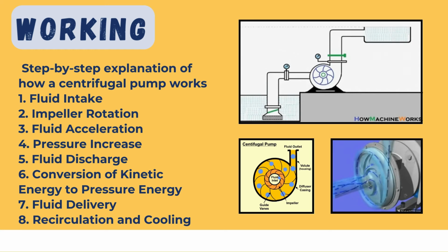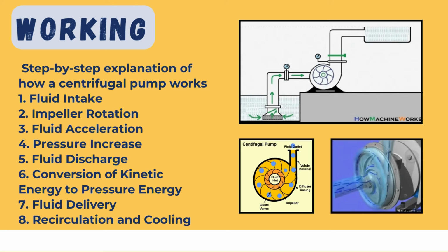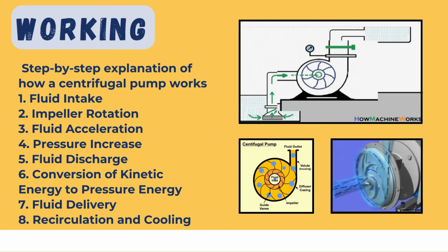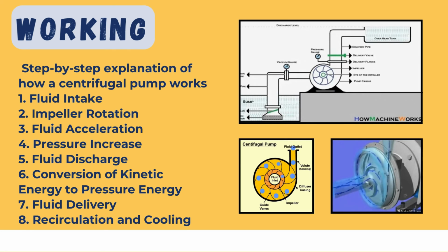As the pump gets pressurized, the temperature of the pump also increases, which increases the probability of the pump getting damaged. So due to this, a recirculation and cooling assembly is provided in some centrifugal pumps. Guys, some centrifugal pumps may have features such as a recirculation line or cooling jackets to maintain the fluid temperature and prevent overheating during operation.